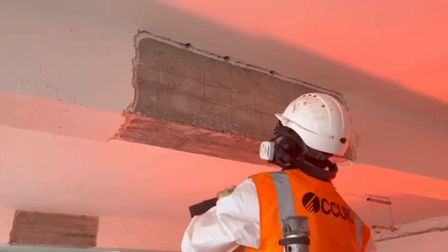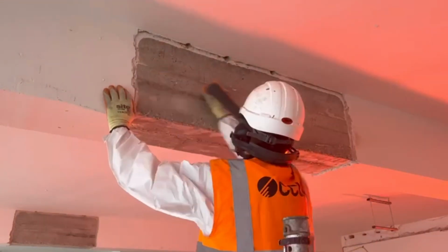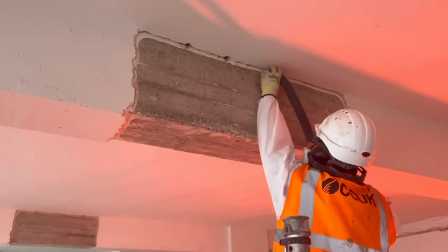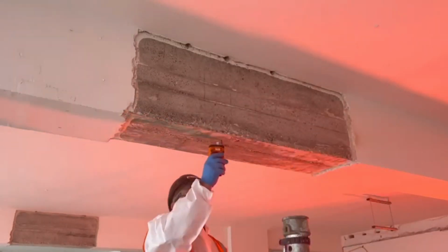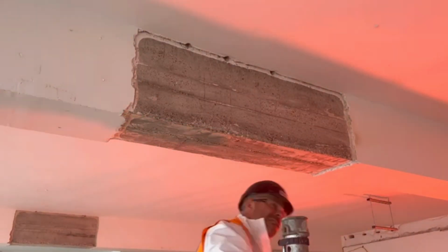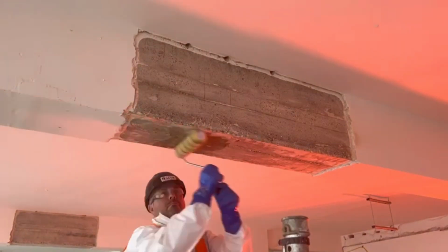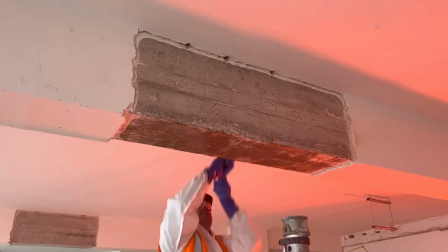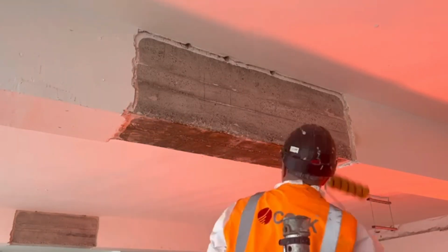So that's another thing to note in terms of application. You use pure epoxy to prime the area so that epoxy can soak into concrete and you get better bond. Then they apply first coat of thickened epoxy, which is the white color epoxy we are seeing. So once that coat is applied, they unroll the first layer of carbon fiber. Then put another coat of epoxy, then another layer, and that's how they build up the number of layers.